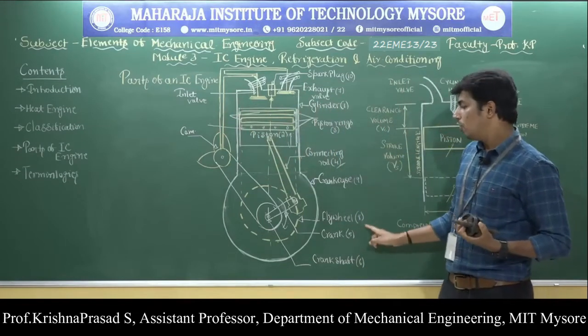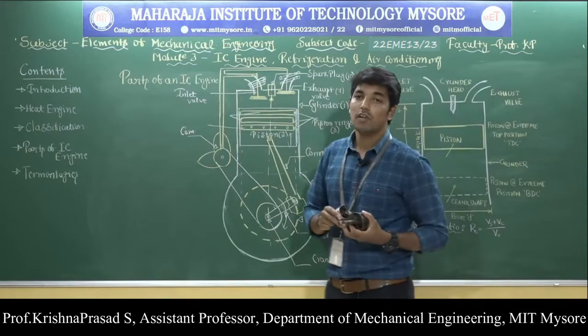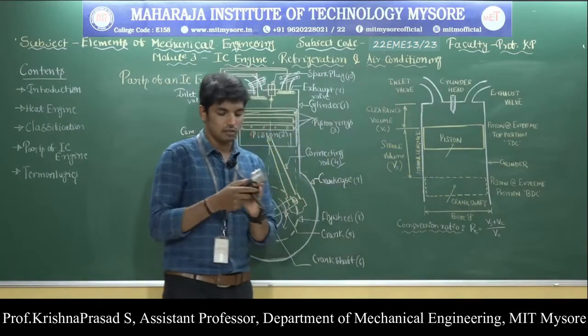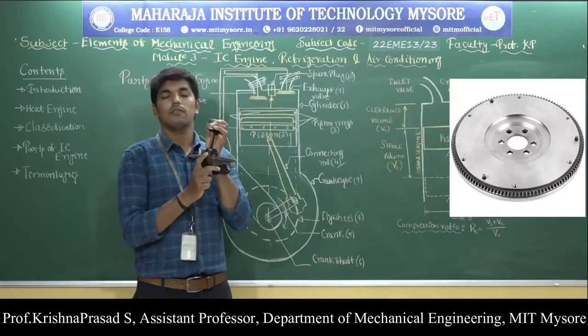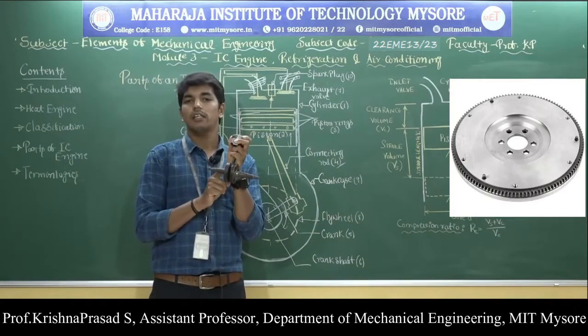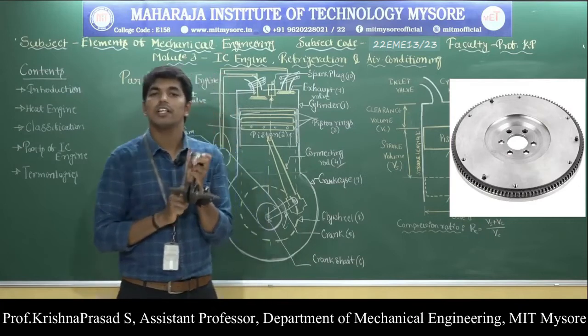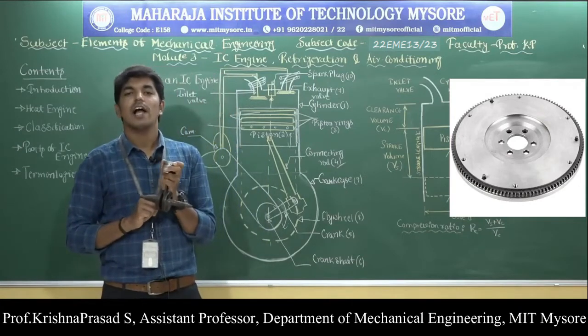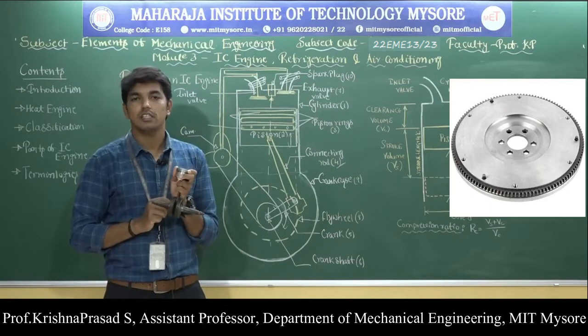Next, the eighth one, the flywheel. The flywheel is nothing but a heavy wheel. So this is the flywheel. The flywheel is a heavy wheel mounted on the crankshaft of the engine, and it stores the energy during the power stroke and supplies the same energy during the other three strokes.